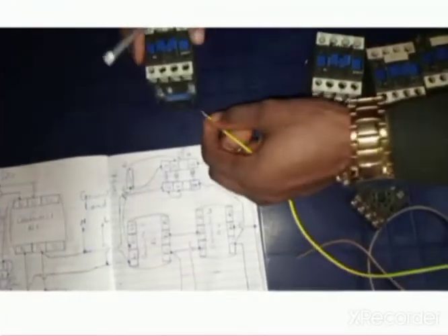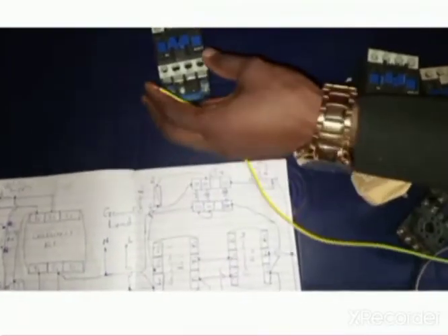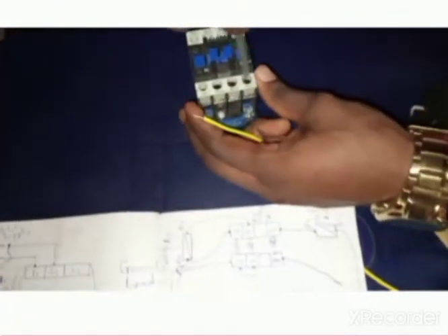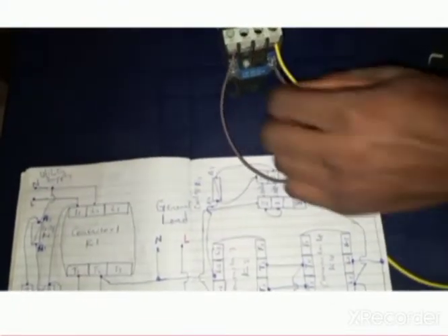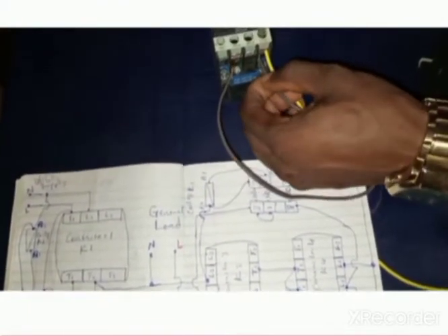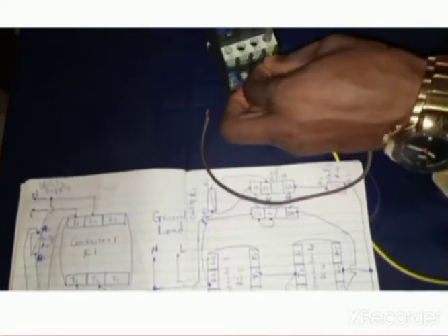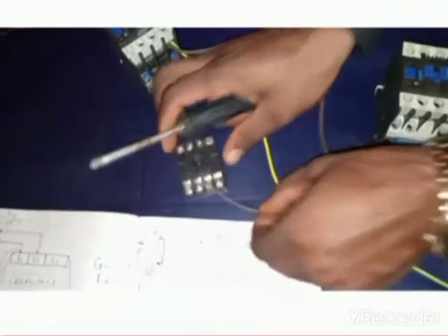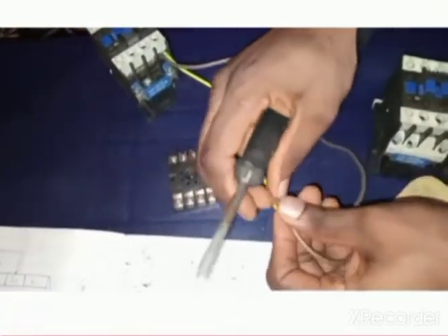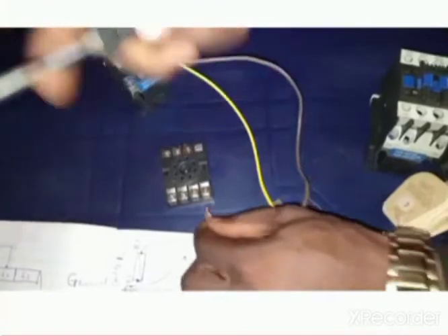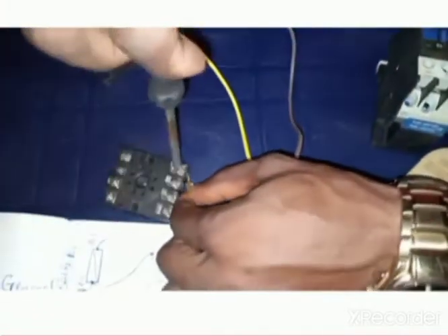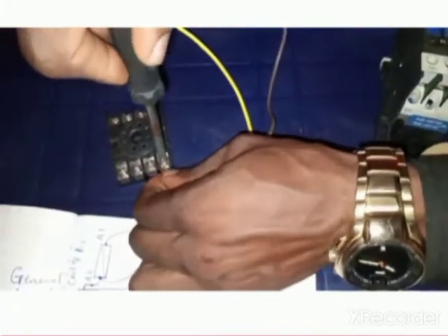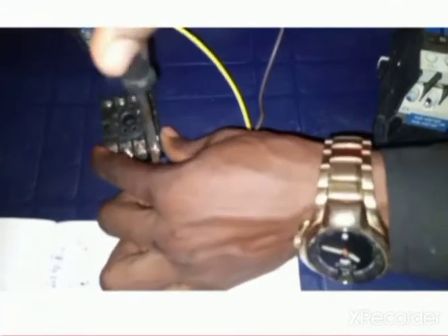So where am I going to connect it? L1, and this is L1 of this contactor here, and from L1 also there is a wire going to 2, so I'm going to connect this together with this one that is going to 2, just like this. Alright, so from this L1 goes to 2 of the pin relay. So this is 2 of this pin relay. I'm using an 8-pin relay. It depends on the pin relay you're using. You can use 11 pin, but make sure that you connect according to the instruction I gave: normally close to normally close, normally open to normally open.